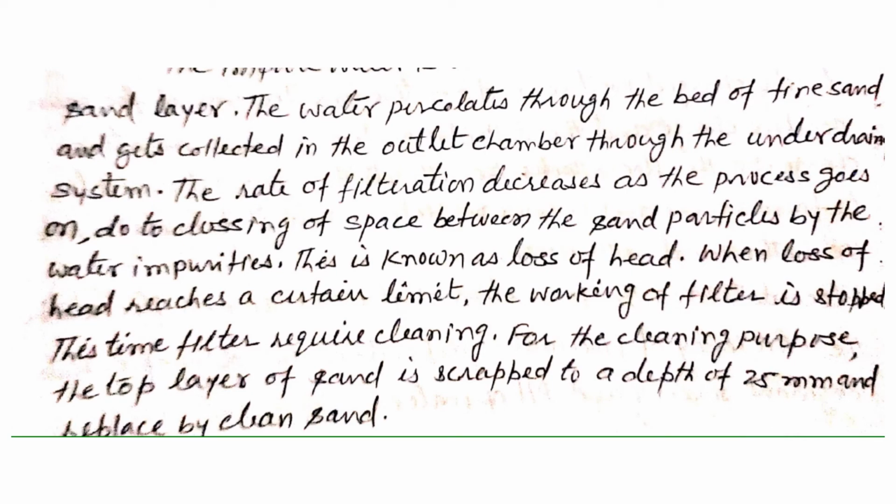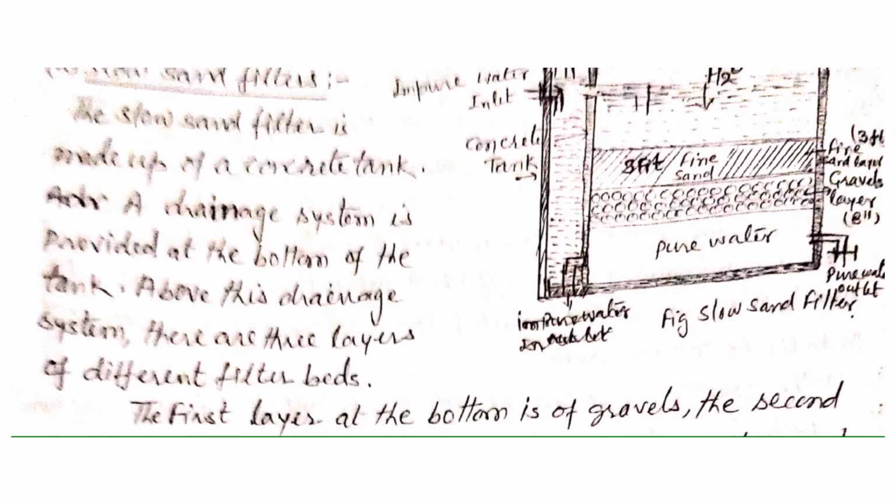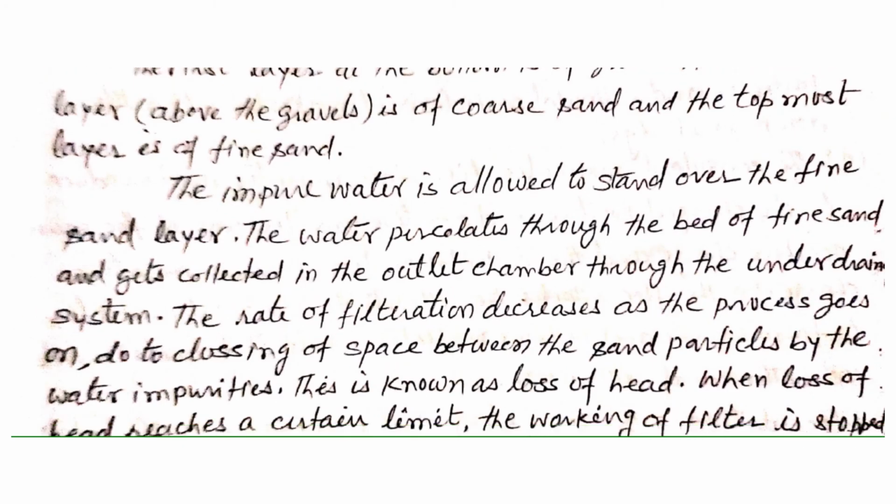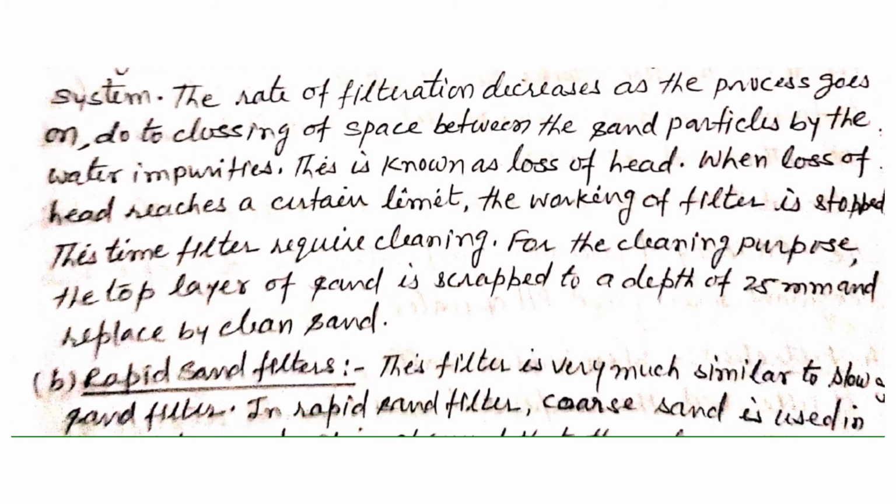After some time, the filtration will stop, because the very fine particles get trapped in the sand layer and stop the water from passing through the bed. Then we have to stop the supply, scrape out this fine sand layer, put in fresh fine sand, and start filtration again. So this is the whole process of purification of the water.